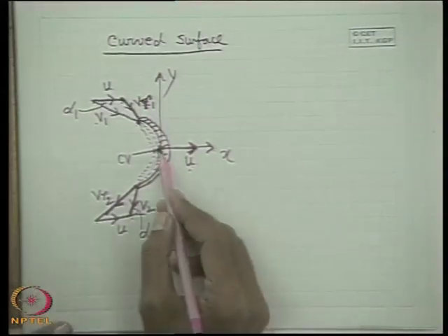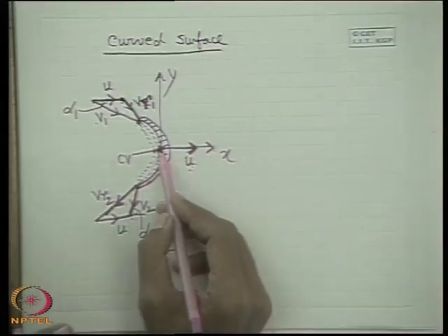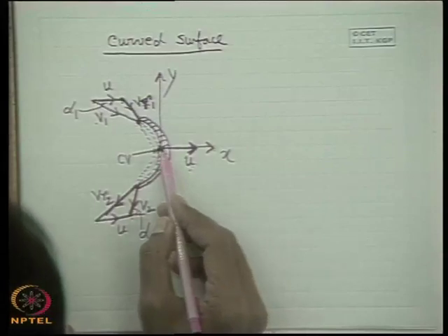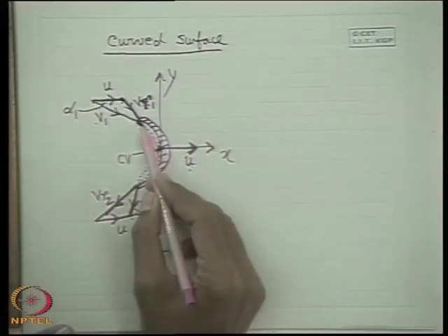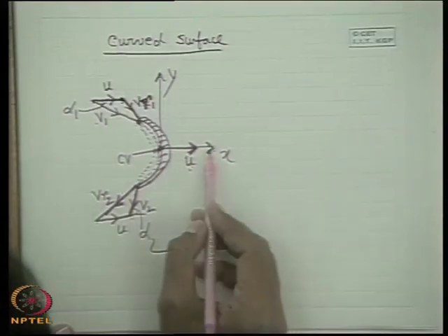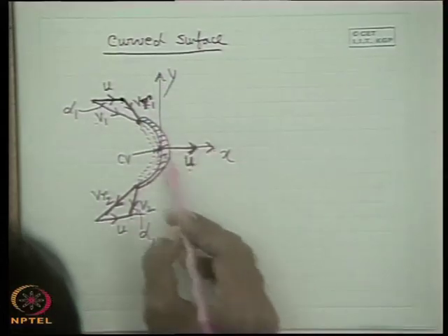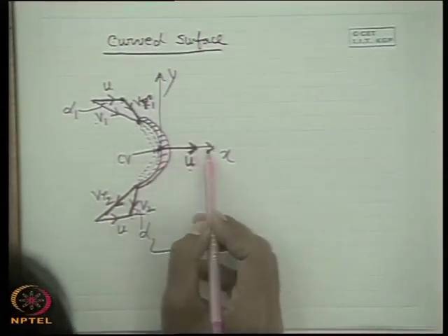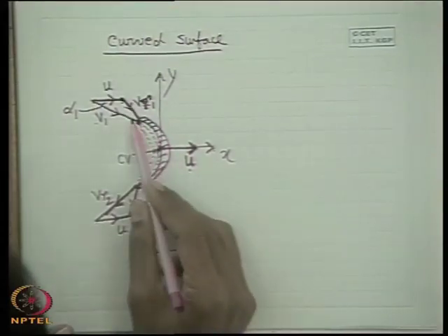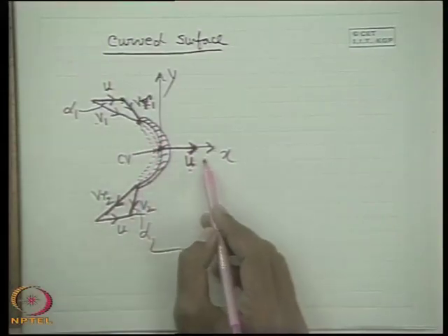Now, if we analyze this with the momentum theorem, we can apply it for both x and y direction, but usually we are interested in finding the force acting on this curved surface because of the flow of the liquid. We are not much interested in the force in the y direction, because the curved surface is moving in this direction. We are finding the power generated or work done to cause this motion by the flow of fluid. So, therefore, we are only interested in Fx.